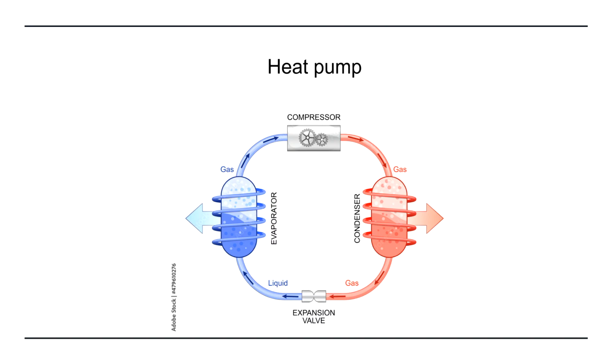Okay, so if you want to play with some numbers here just to think about it, R410A on the evaporator when it's a gas or a vapor will be about 40 degrees. When it goes over to the other side of the compressor, it'll be about 110, and it's going to reject that heat out through the system and then back around and start the whole process over again. It just continually cycles that way.